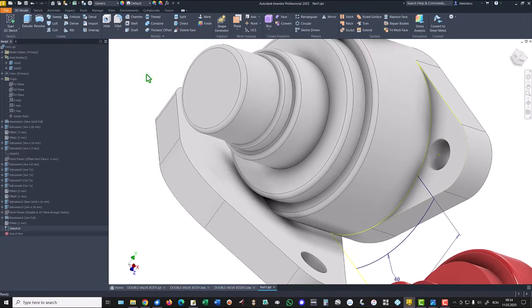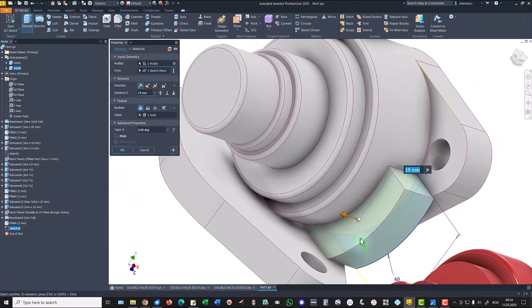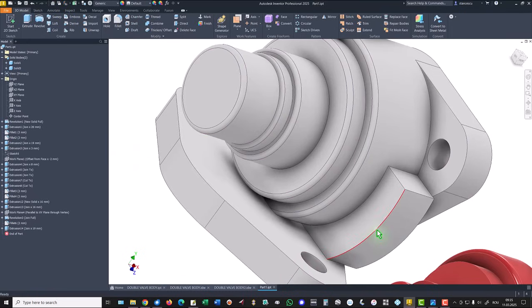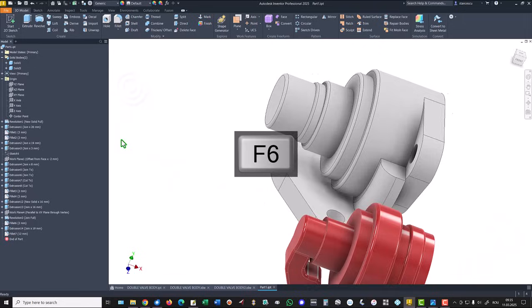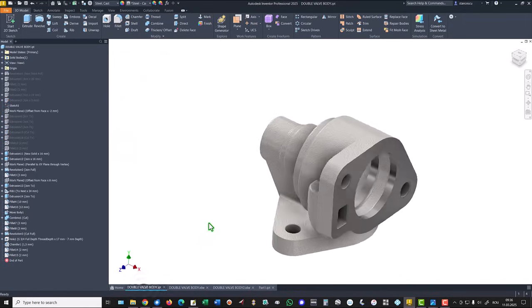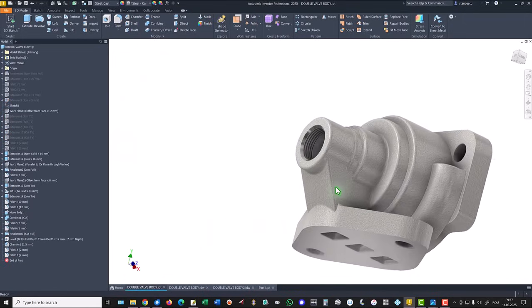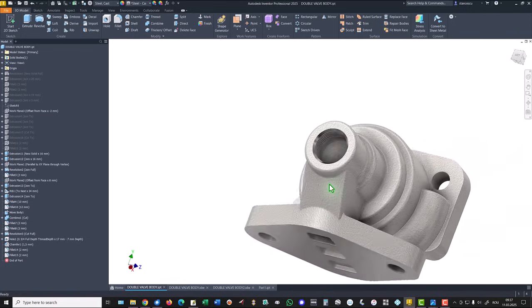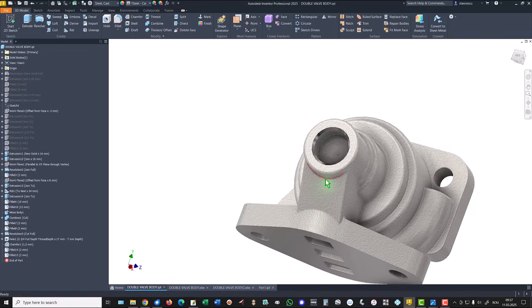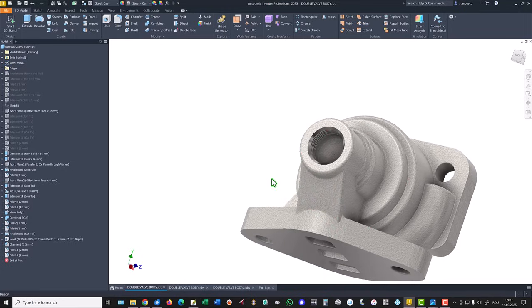Finish sketch, extrude. This area is a closed contour. 19 is the thickness. Okay, and we apply a fillet of 12 here, not to forget. This feature can be considered a rib. We need to draw only one line, a midline here.